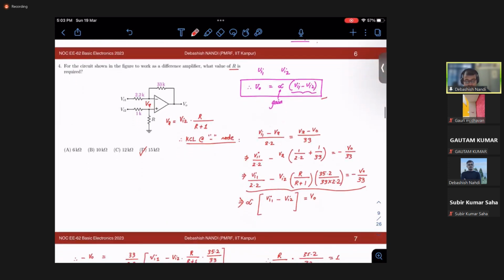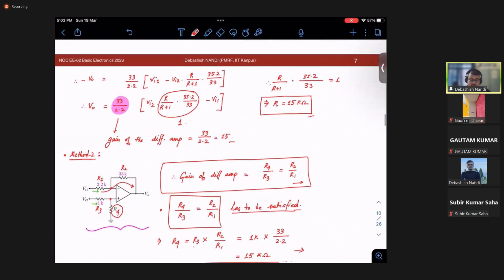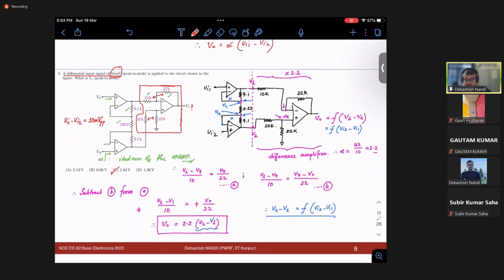Then we have used this improved differential amplifier, or sometimes it is called instrumentation amplifier also. So the purpose behind using this circuit is twofold. One is the input resistance you are looking at is infinite, which you are not getting in this difference amplifier. So you are going in for the improved differential amplifier. Basically, it is nothing but two stages of differential amplifier, right?